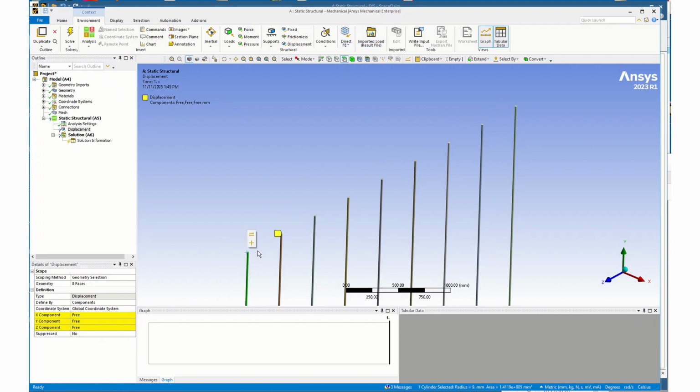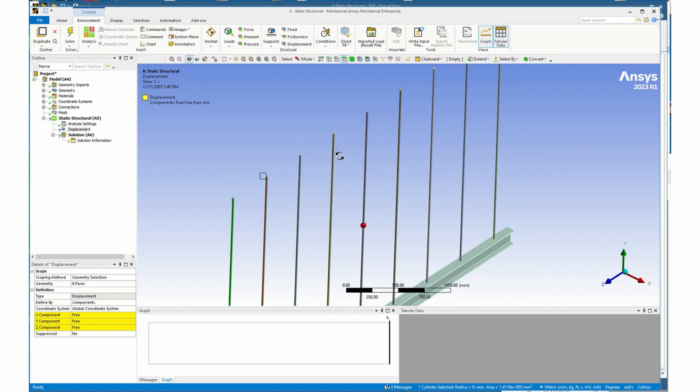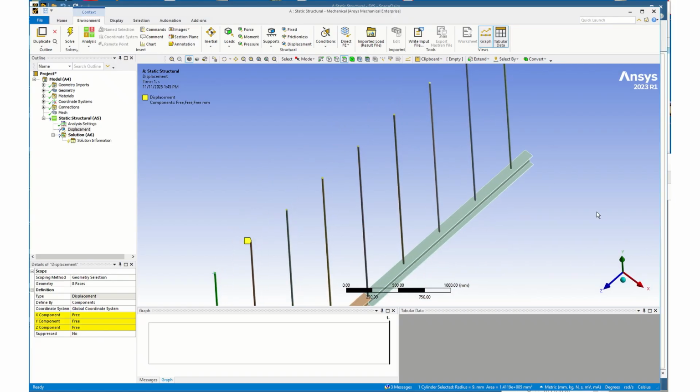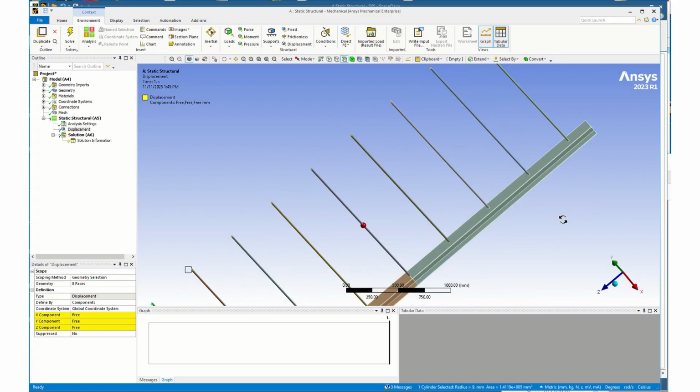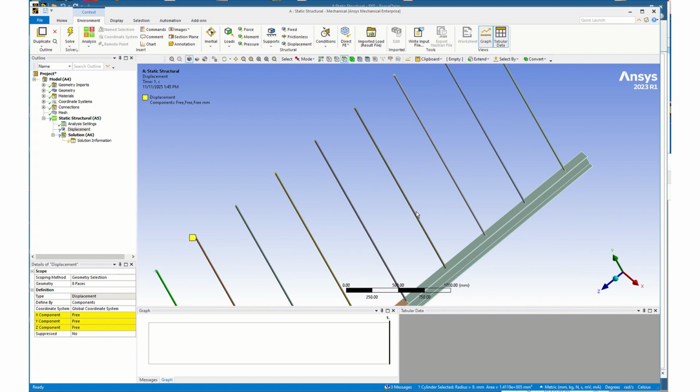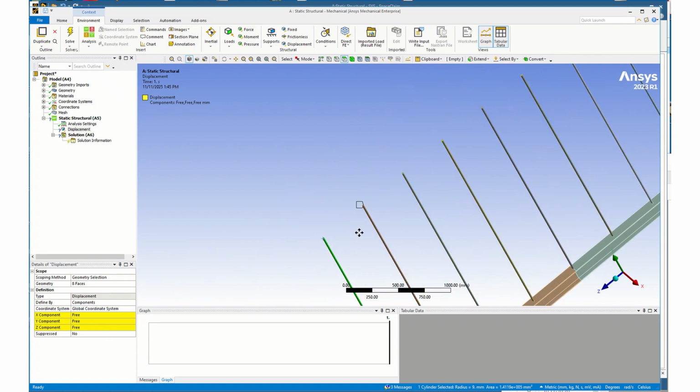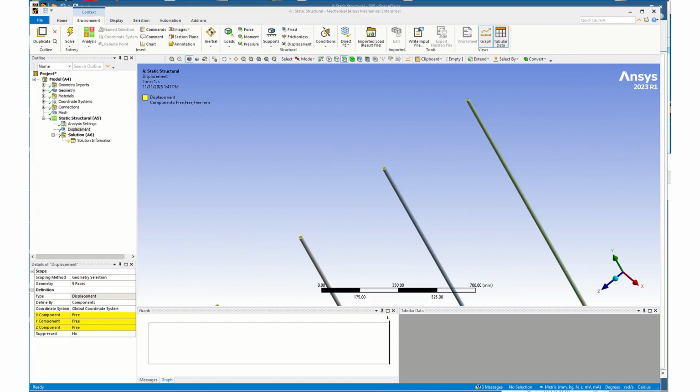I can see that one, and the thing you have to be careful with is that oftentimes, like I just did, you'll select the face of the circular rod, and that's not the face that you want to get. So you've got to be careful with that. I'm going to start over and grab those top faces. Having done that, you can now see that I have 9 faces here.